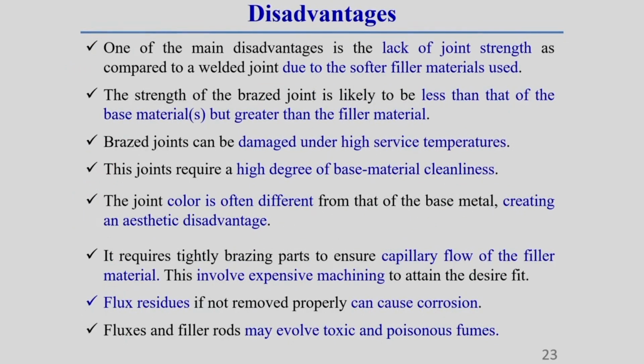This is the disadvantage of the brazing process. Generally there is a lack of joint strength as compared to a welded joint due to the softer filler material used. The strength of the braze joint is likely to be less than that of the base material, but greater than the filler material. So, whatever joint we are making, its strength is lesser than the base material, but its strength is higher than the filler material.